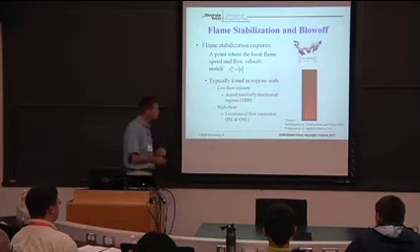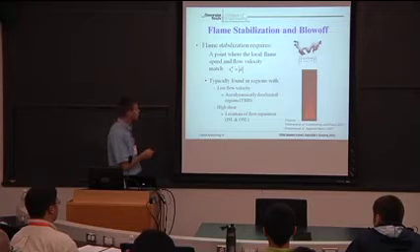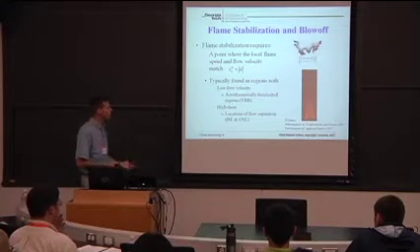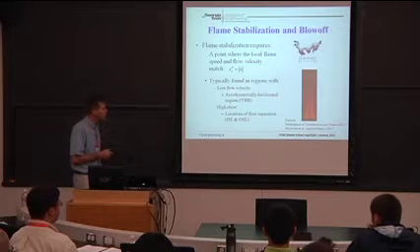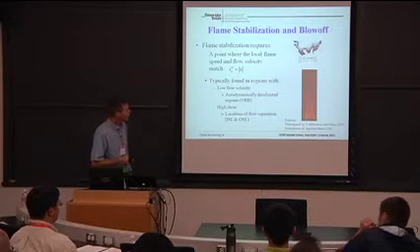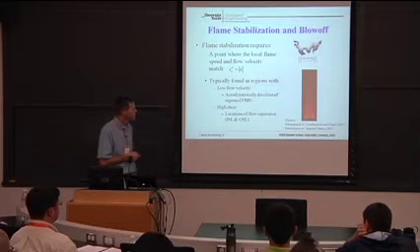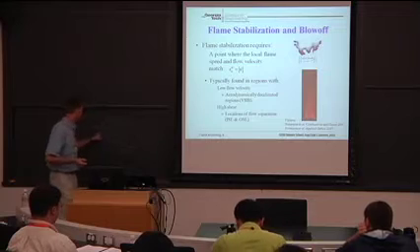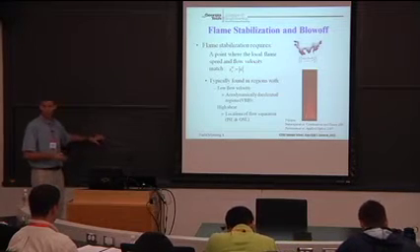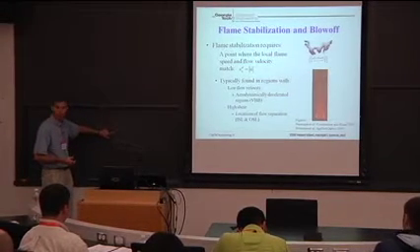All right? Well, again, on average, this flow velocity is much, much greater than the flame speed. So typically, you'll find this inequality in low velocity regions, in low flow velocity regions. For example, in aerodynamically decelerated regions, VBB stands for Vortex Breakdown Bubble. Sorry for not writing that out. But think about this picture that I drew here.